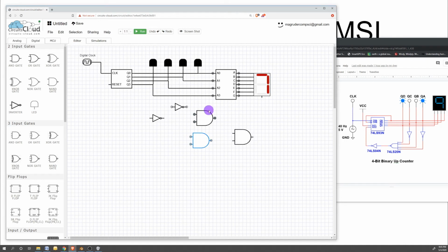So instead of using NAND, I'm going to use AND gates because this will be a relatively easy way to pull a very specific combination off these wires, because we don't want it resetting for anything other than our ceiling value. So what I want is 1010, so I'm going to take the 2 to the 0 and the 2 squared place, and pull these off. I'm going to negate them, and that'll be our first AND gate. I'm going to pull the other 2 signals, which would both be on, or 1, or high, when we would otherwise see A here, and I'm going to AND those together.